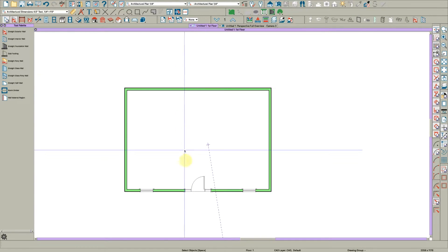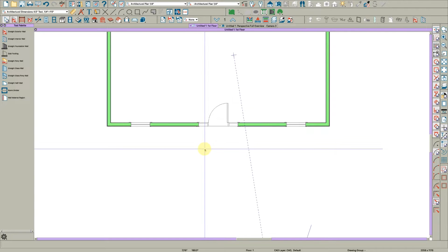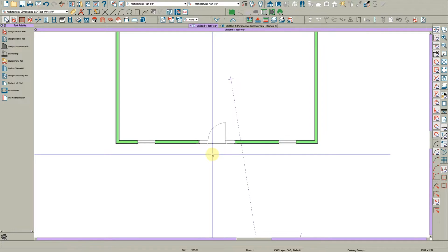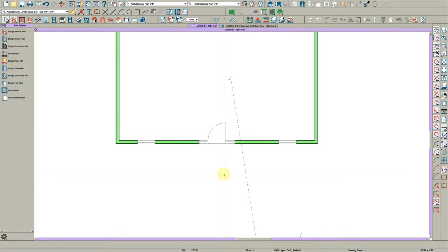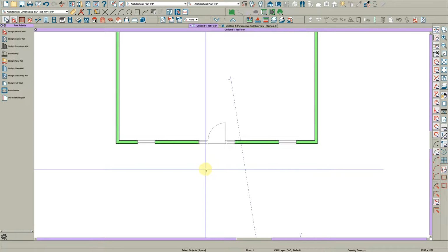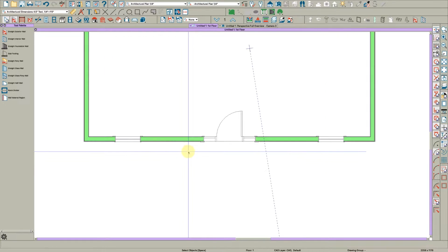Let's go over here to the floor plan. One thing I discovered in doing this is that I'm going to use soffits for a majority of this trim detail. If you use soffits and slabs and things like that, and you set their elevation and you don't have a terrain, things are fine. But as soon as you add the terrain, all those items will adjust on their own to be the elevation above the terrain. So we don't want that. We don't want these things moving later.